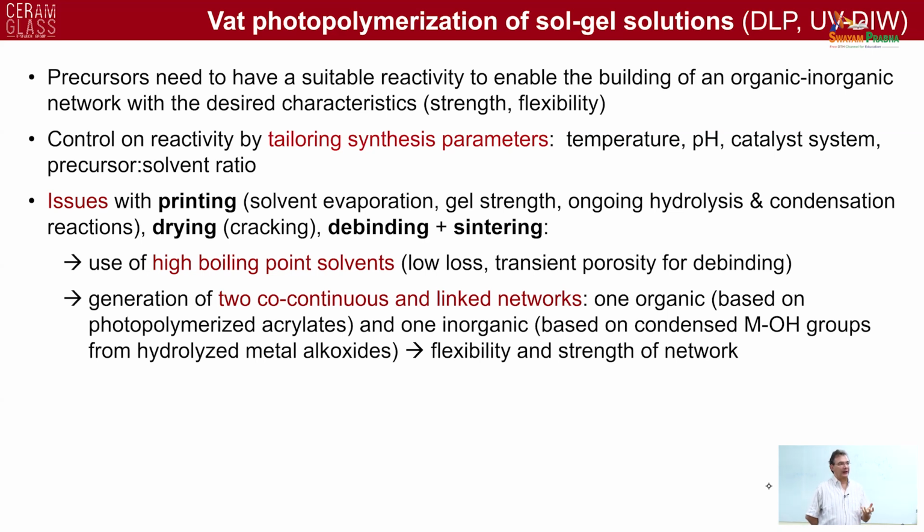You have issues with gel strength. You have these ongoing hydrolysis and condensation reactions, which change the viscosity of the system. And even if you're able to print, then you have issues with drying, because the gel is micro and mesoporous.